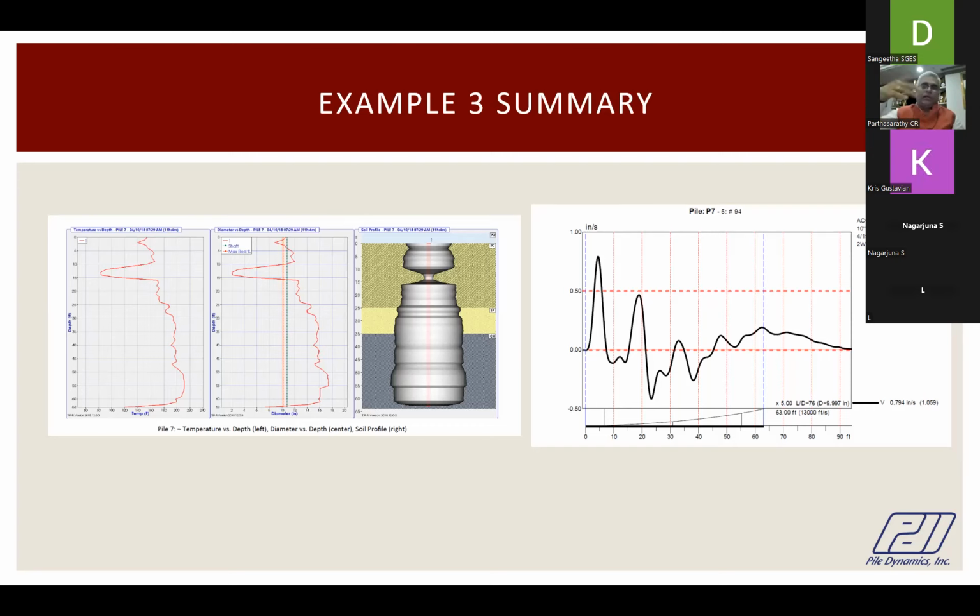They realized this only when they started excavating to the basement after installing all the 2,000 piles. So what if you would have done this thermal integrity profile in the same project? With the first few piles, you would have already known there is a severe problem in the drilled shafts. They could go to the drawing board, root cause that issue, probably change the procedures. They would have mitigated, right? Now the piling is done. You spent around $8-9 million. Now the remedial measures to counteract or make some other changes in the foundation systems are going to cost them another $4-5 million.